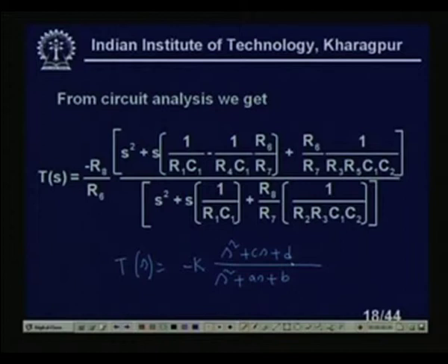Now, for this reason all these components can be realized by some resistances and capacitances. So, if I purposefully make that portion 0, obviously I can get it. Suppose in this case I make C 0 and D 0, so it will be a high pass structure, right. Similarly, if I make R6 infinite, in that case I can make it a low pass or band pass structure, like that it goes, right. So, with this type of structures obviously I can generate any filter function.